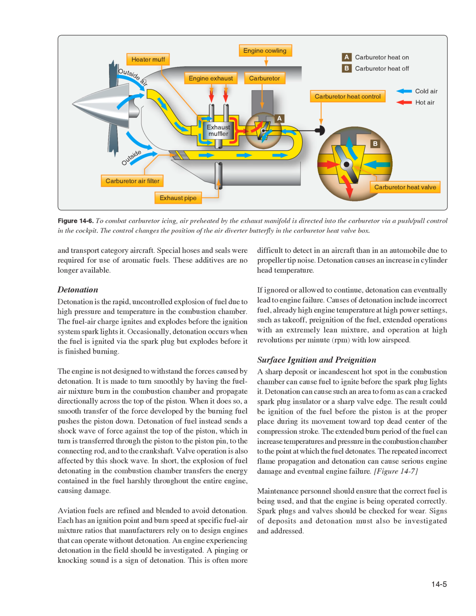Figure 14.7. Maintenance personnel should ensure that the correct fuel is being used, and that the engine is being operated correctly. Spark plugs and valves should be checked for wear. Signs of deposits and detonation must also be investigated and addressed.